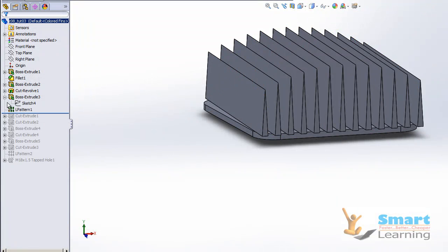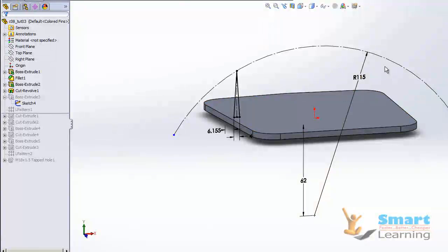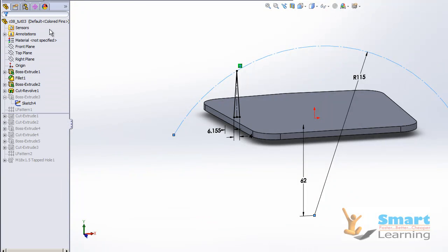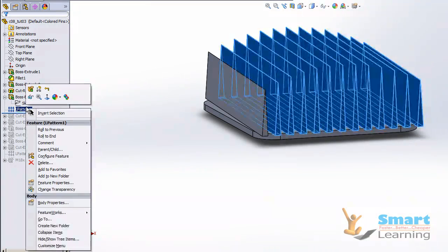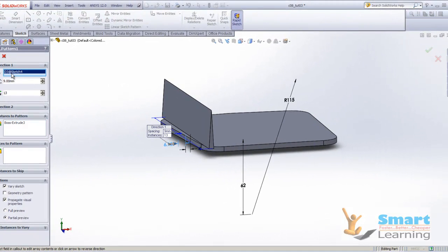Then you will go for the pattern which will be created like this. So before creating this, you can just look over it. Whatever feature you have created is basically constant through this curvature, and then you can directly refer through this curve. And when you go for the pattern, this is exactly done through the line pattern, but here the reference we have taken is this particular sketch.